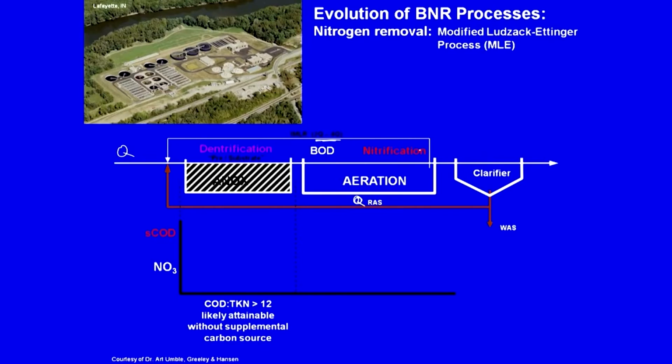But without disturbing that, what can I do? I can look at the internal recycle of the MLSS, 2Q to 4Q. So, nitrate is being recycled, right, but now only relatively less nitrate will leave the system. We will see why in general. So, soluble COD, higher degradation during this anoxic phase.